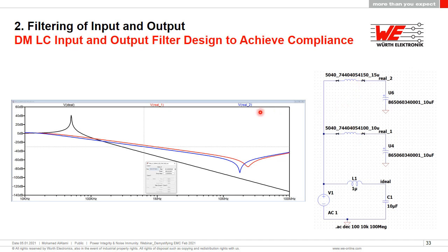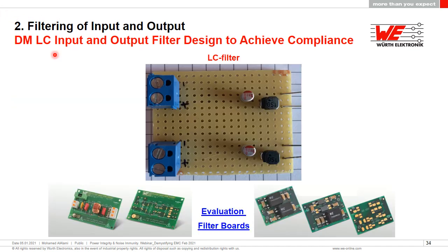That becomes more lossy, that becomes more hot. So it's easier to play, especially when we've got smaller values of capacitance, to play with capacitance and smaller voltages, I should say, to change capacitance value than it is to change inductor values, especially when the current is relatively high. So keep that in the back of the mind.